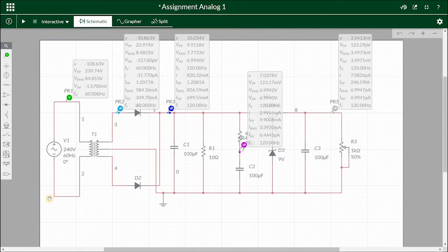The connection of the Zener diode acts as a voltage regulator. A complete and stabilized power can be obtained by using the rectifier diodes to change the AC power to DC power. The rectified voltage is filtered to reduce the ripple on the rectified waveform. A Zener diode is then used to regulate the voltage to its desired final value. Okay, moving on to the waveforms.